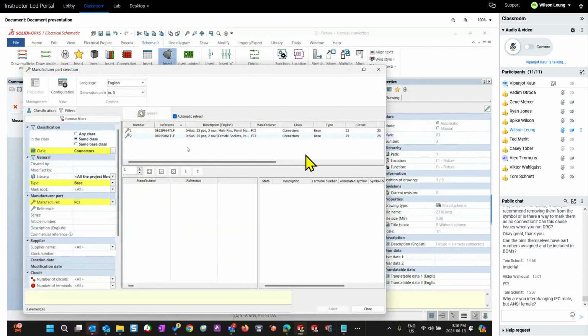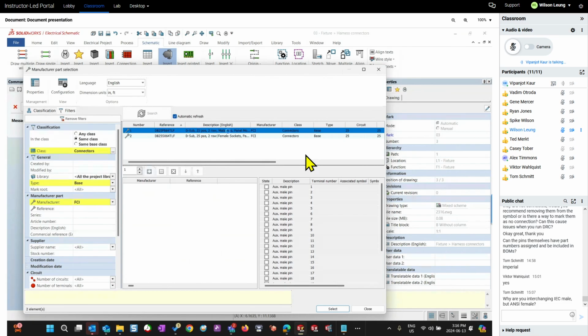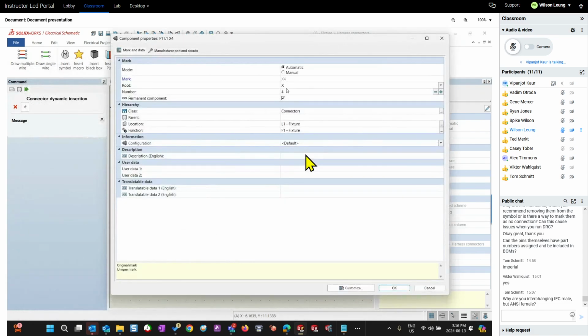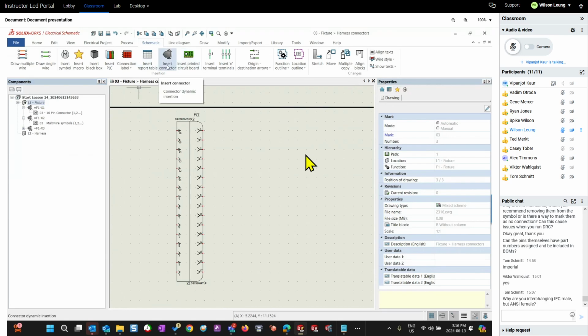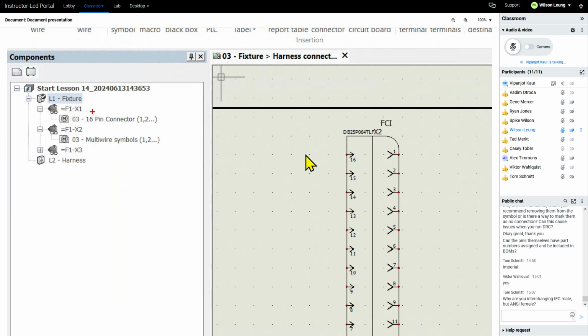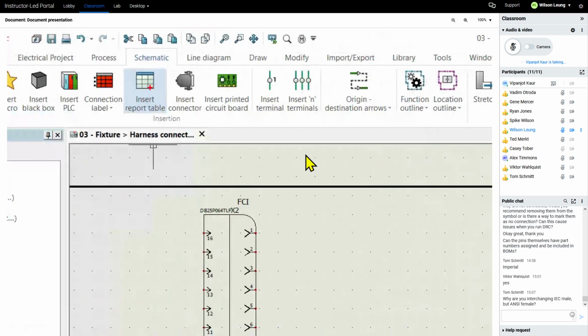So when I create a brand new one, if I'm picking that I'm using this male pin connector, double clicking, clicking OK, and then it's asking me, VIP, it's going to be X4. I said OK. Then right away it's asking me to go insert the pins. But if you tell me, VIP, you were not supposed to use that part number, use something else, then I'll say, oh man, I have to cancel the whole step, start all over again. In this case, all the steps are embedded together in one click. So when I finish one, automatically it starts the next step, next step, next step. If I make one mistake and hit escape, I've lost all the work now.